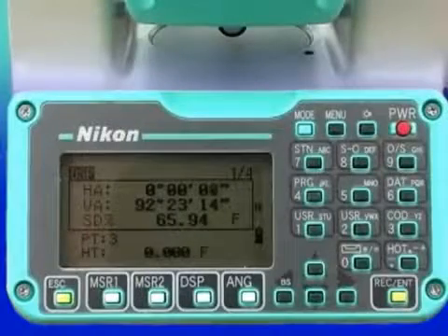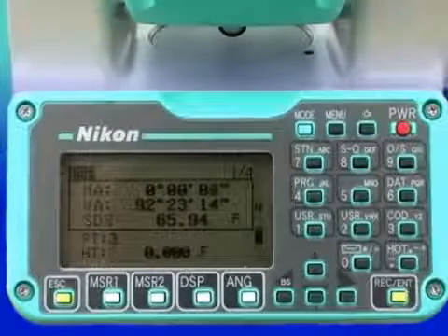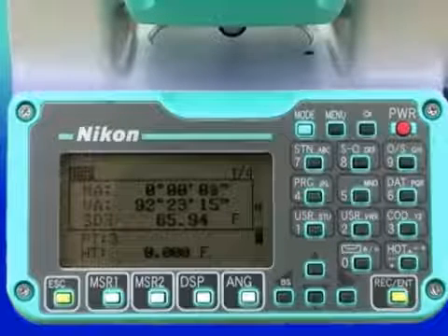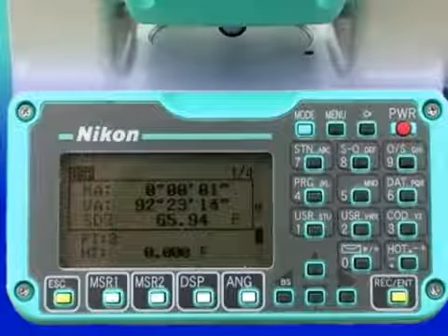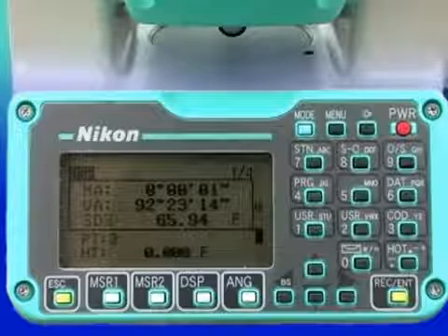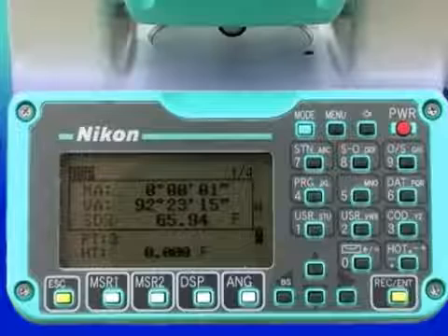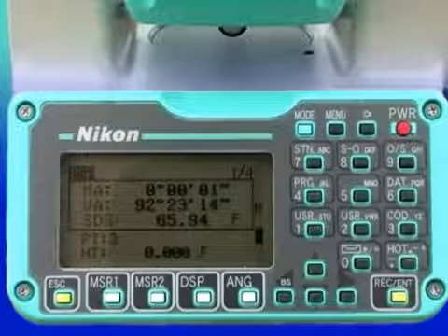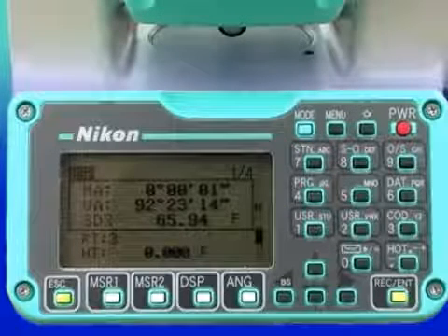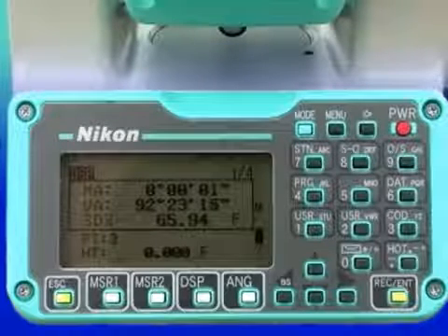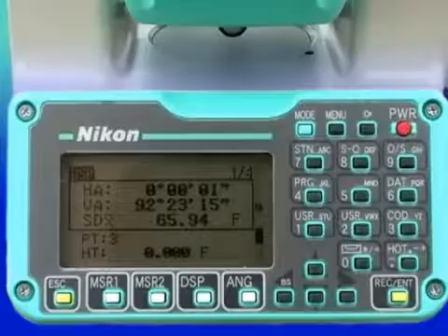point being monitored. It should be noted that the accuracy of a 5-second survey instrument is approximately 1/8 of an inch for a point 400 feet in distance. Although the Nikon NPL-352 is rated as a 5-second machine, its performance is always better than this. The level of accuracy should be more than sufficient for the purposes of monitoring points in the urban search and rescue environment.